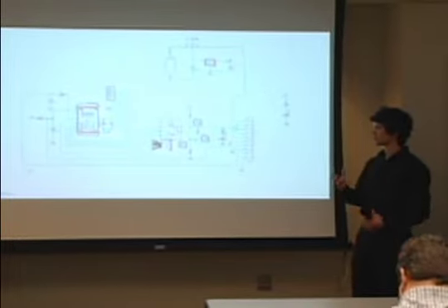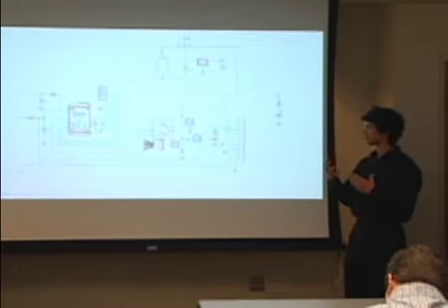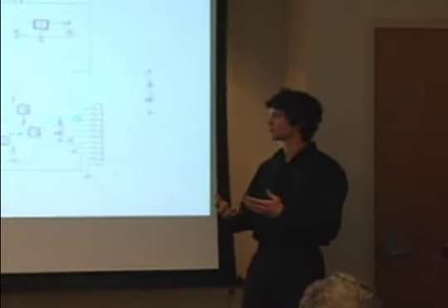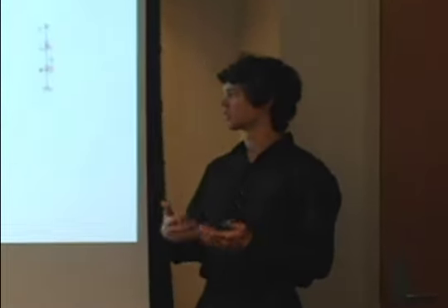The microcontroller basically sees a square wave, collects the data from that, finds what the frequency is at this moment, does a calculation, and sends the data out through the RS-485 serial chip here to our PC. And we also have a selectable power supply up here.